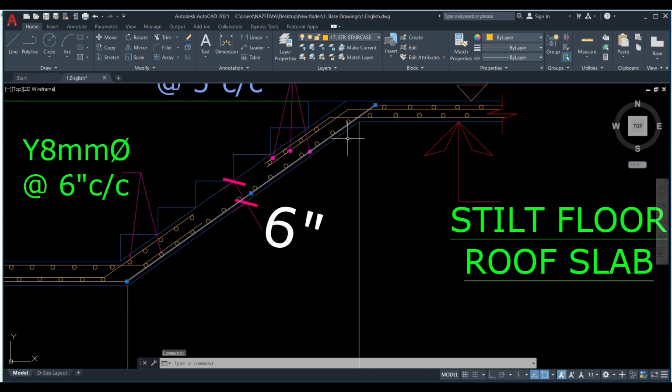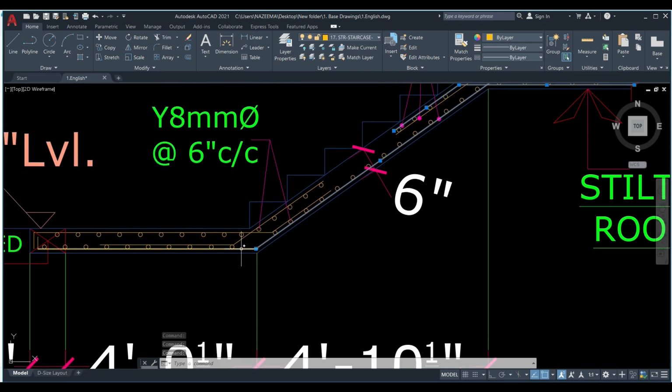The bottom rebar is there, it becomes a top rebar over here. Then this bottom rebar is there, it becomes the top rebar over here. The extra bar they have provided is not required as such. So this bottom rebar is going to continue completely straight like this. Okay, then this top bar will become the bottom rebar like this. So this is what they have done over here. So again, we have a crisscrossing being shown over here. Okay, all right. So please keep this in mind.